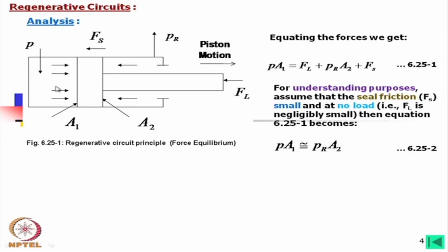In that case, we will find that this will generate a pressure. Say the pressure relief valve is set at any pressure, say 5 megapascals. Then 5 megapascal pressure must be generated here for the leakage. Then whatever P is required here can also be calculated. That means at that condition we can write down this equation, or in other words, if some resistance is put here, then we can generate the pressure here.